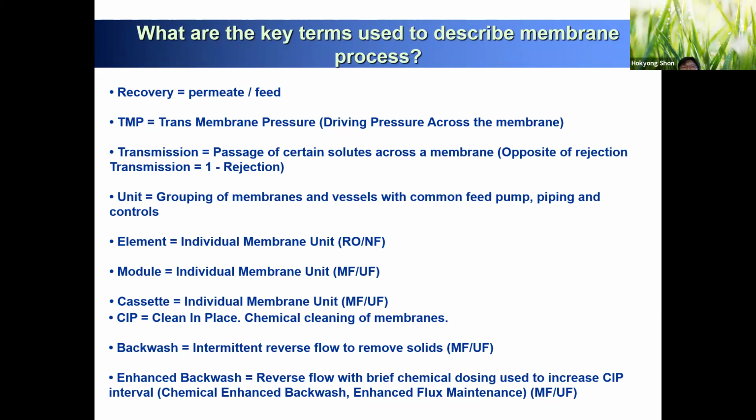So all combined, water will be the whole capacity of your water design, right? So let's say unit. Okay, 1 unit I want to design around 1 megaliter per day. So your target design capacity is 250 megaliter per day of the Sydney desalination plant. So multiply by 1 unit, 1 megaliter, multiply by 250. So you design 250 megaliter per day, 250 units.